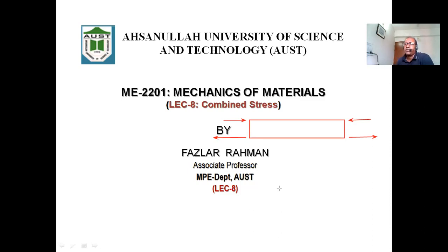So in which direction does shear force work? Parallel to the cross section. So everywhere shear force is working downward, or might be upward, but parallel to the cross section. So if I take a point in the beam, say right over here, how many forces are working at this point? One is compressive stress, right, due to the bending.